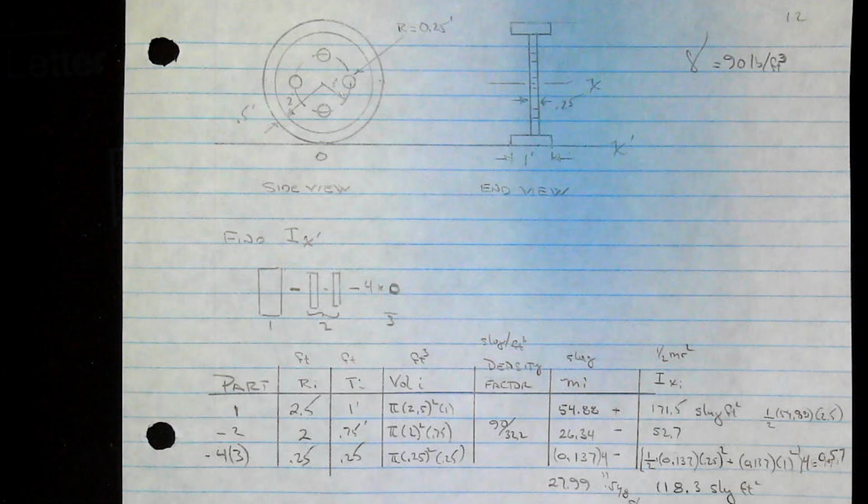This minus that leaves us with 34.22 kilogram meter squared. Now, let's just go back to our previous picture real quick. Once we have Z1, we want to move the axis 1.5 meters over. Not a problem. We're going to use the parallel axis theorem. So IZ2 will be IZ1, plus the total mass, that's why we computed it, moved over 1.5 meters squared. Bam. 418.6 kilogram meter squared. We're all set.